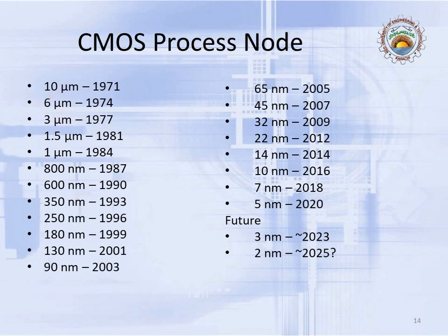So you see the transistor's size has decreased, not only the channel length, in fact, all the parameters decrease in size proportionately, and hence you have a smaller transistor. Once there is a smaller transistor, it means that more transistors can be accommodated in a similar space, and hence the number of transistors gets roughly doubled.